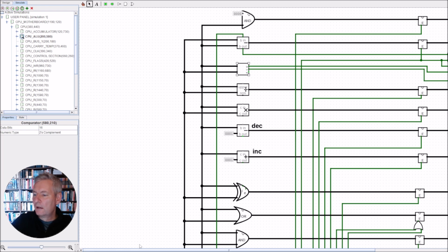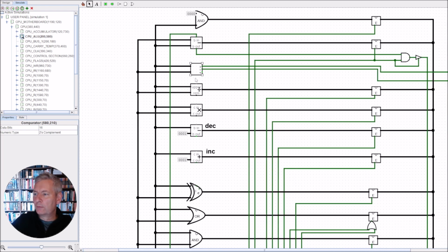So it means that whenever we have, for example, a negative number like minus 10, minus 10 is actually smaller than minus 5. But if we were to put that through the little comparator that we used here, it wouldn't have dealt with negative numbers. It would have said that the number minus 10 is larger than minus 5 because the actual value 10 is a larger value than 5, but it's negative. Negative works in the opposite direction. So that's why we've had to put in this 2's complement comparator.